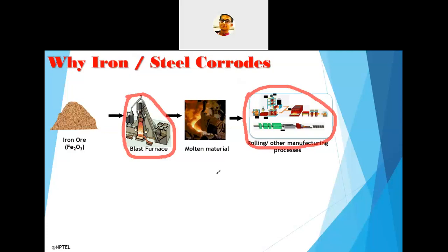maximum energy. So if you expose these types of materials, or any material which has high energy, or more residual stress on the surface, the material becomes more reactive. And as it becomes more reactive, when you place it in any extreme environment, it will surely undergo a corrosion mechanism or corrosion process.